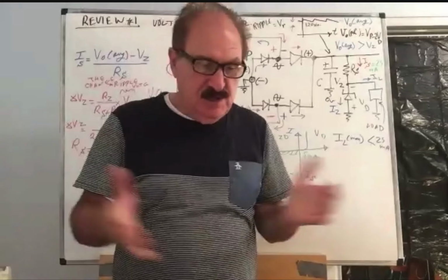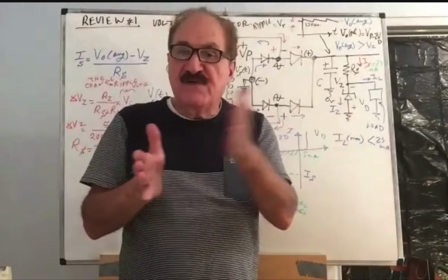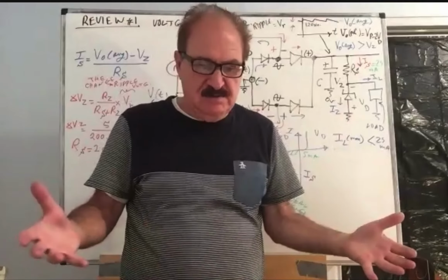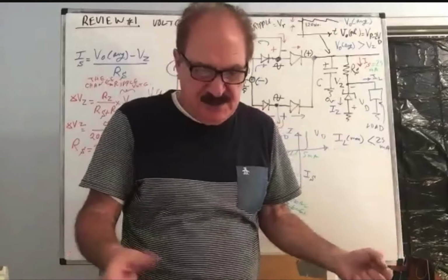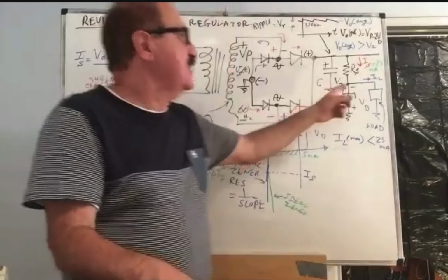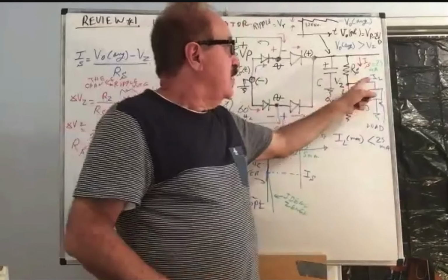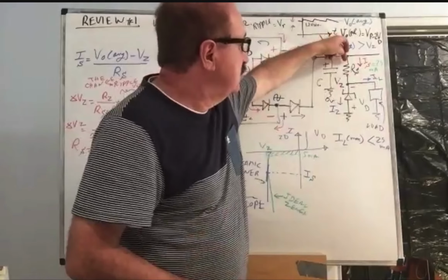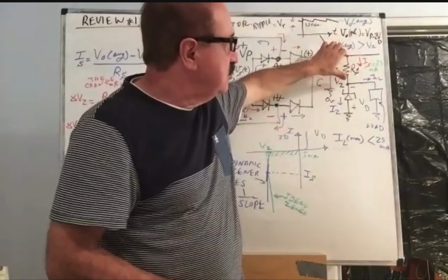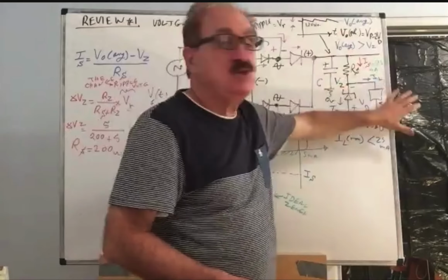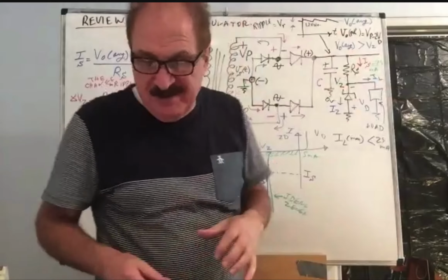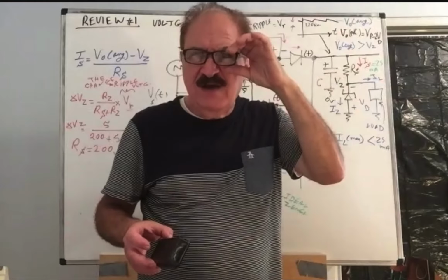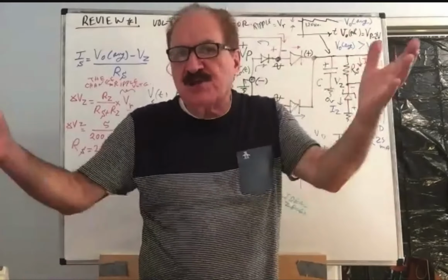Here comes the buffered voltage regulator, which is more like a realistic voltage regulator. It is a legitimate power supply, basically. That is a transistor. So, if you're demanding a load current that apparently exceeds the limit that you have set in the RS, let us use a buffer, a transistor. Think of it like an emitter follower. No, we haven't covered emitter followers yet. Well, just a transistor.